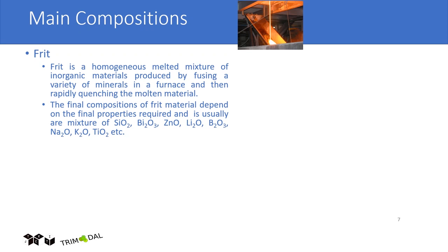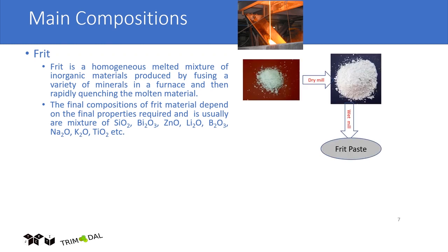And most print integrators are associated with a frit manufacturer. They are pretty much linked together and tailor-made. Pigments are pretty much pigments. So these frits are furnace cooked and quenched rapidly, and you get something like a rock glass. This gets into the milling system, dry milled, brought down to about 7-8 micron. That's what the enamel particle size is about.